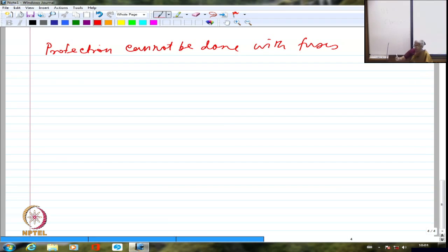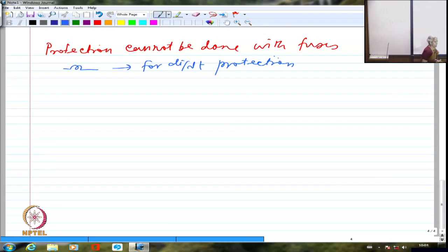Just like what we said in the case of thyristors, similarly inductance is used for di by dt protection. But snubbers are not very commonly used with MOSFETs, because the device itself is somewhat capacitive. You don't want to intervene with the entire behavior, right?